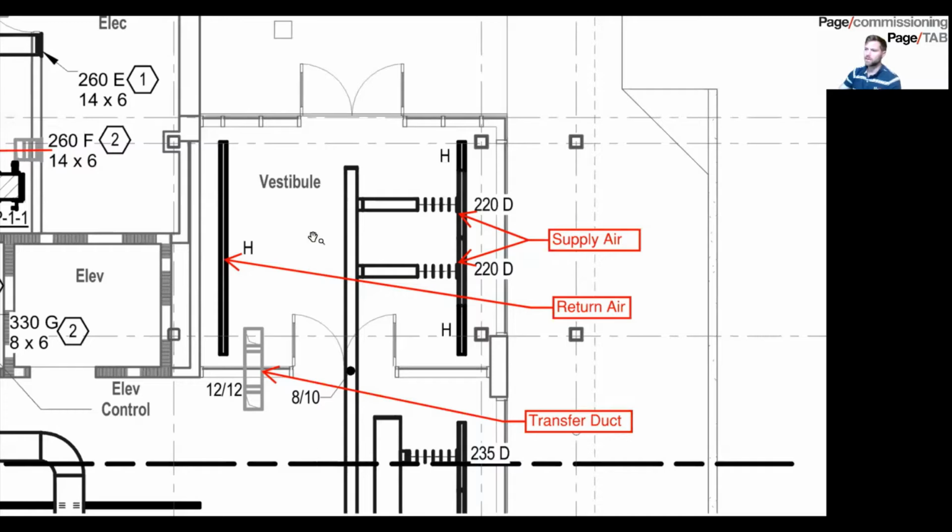So basically you have a well-designed vestibule area. As long as this can keep up with the heat load, it shouldn't have any pressure issues. So why are we having ceiling tiles lift out of the ceiling grid? Well, it's got to be something else outside of this vestibule, or this box was not balanced correctly.